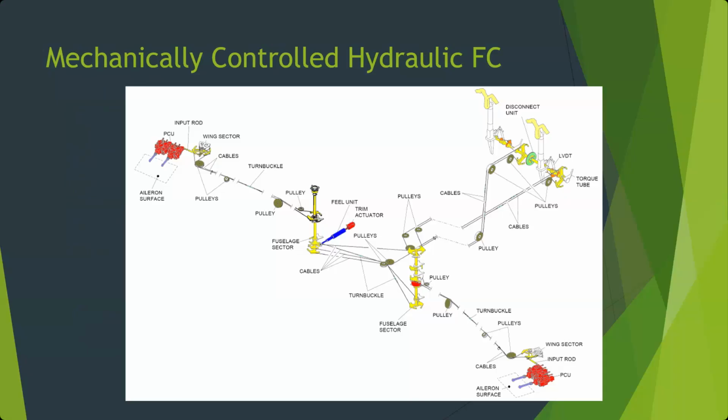Same thing with rudders. Often they have 3 PCUs, or in the case of the 727, it often had an upper and a lower rudder. So it had 2 halves that would normally move together, but it could move one or the other. Elevators, you can just move the left or the right elevator. They're so close to the center line, they don't really cause a rolling moment. They do a little bit, but if you can only move one elevator, the left side or the right side, that's still going to pitch the airplane with minimal roll. Again, the ailerons are way out on the wingtips. That's why they're able to roll the airplane.